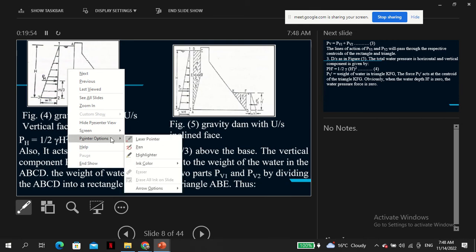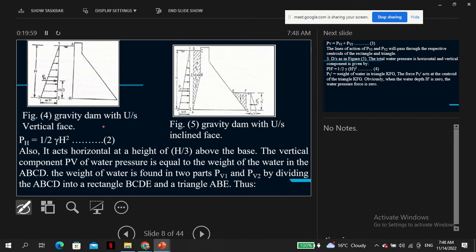They use some notations there, but you know that the pressure variation is such that, here they're using weight, but actually this should be gamma h. And then this is h. And to get the force acting on the dam is to find the area of the pressure diagram. You should be familiar with that.